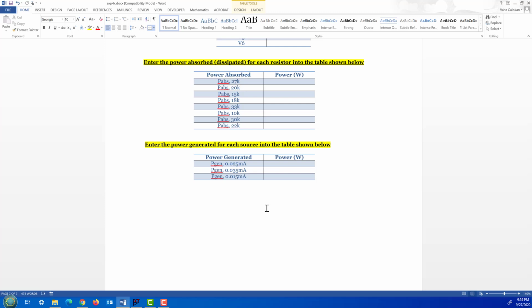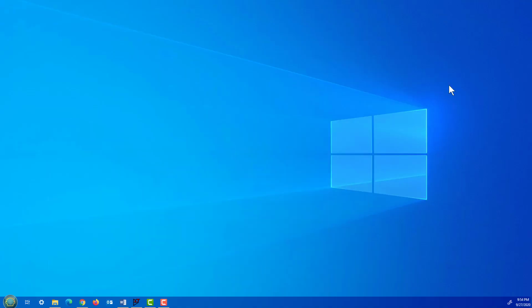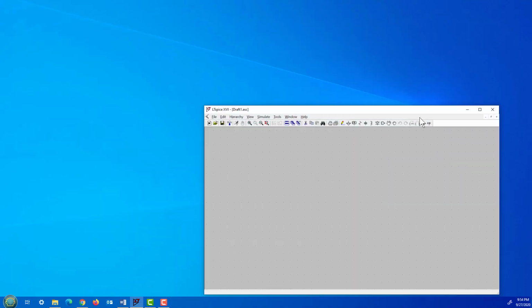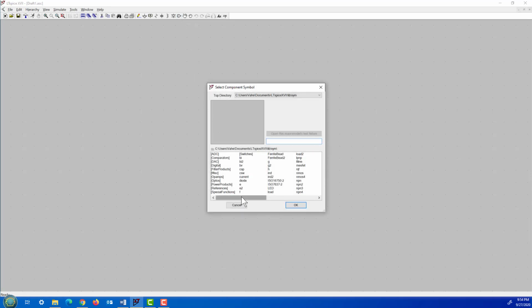Should be pretty straightforward. Now let me show you again, in case you want to see it again, you want to see me do something here with the entering of the components. So let's just enter a circuit with the values, and let me just go through it again just so that you understand what I'm talking about. Okay, so let me go grab a voltage source. You can go here, by the way, and pick your sources, right? Like a current source. Here's a current.